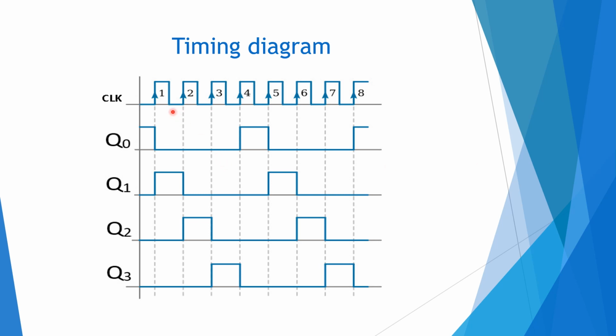And this is a timing diagram. At the first clock, we asynchronously set the flip-flop output. So this 1 will be circulating like this through all the flip-flops. This is the counter waveform. You get a better understanding if you look at this, and this pattern repeats infinitely.